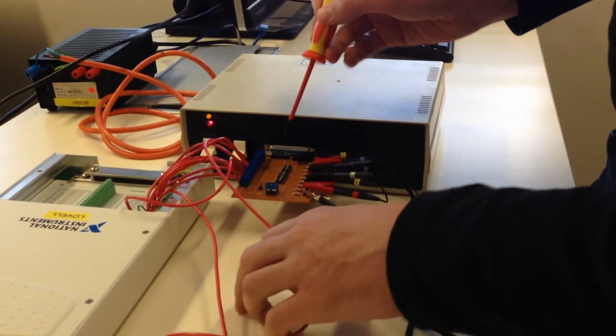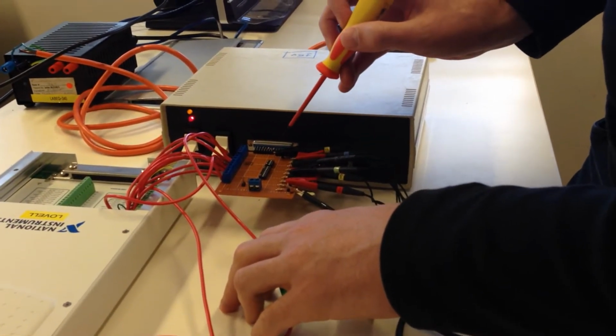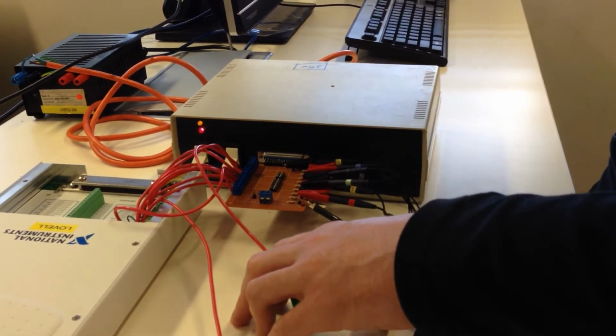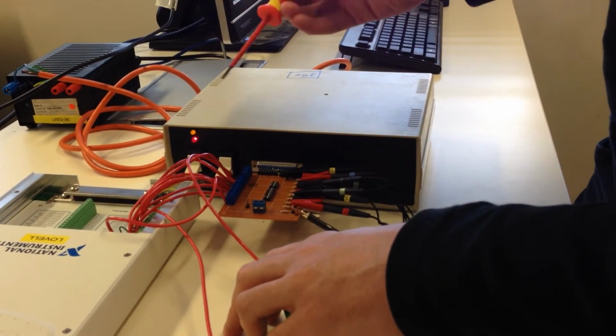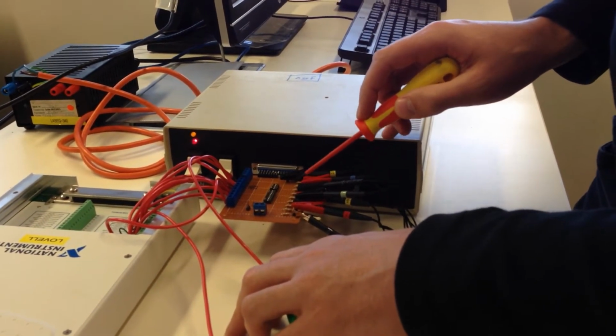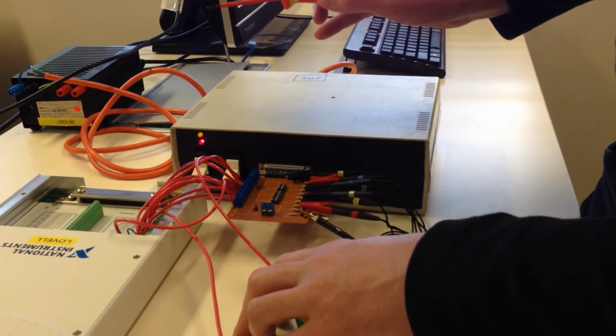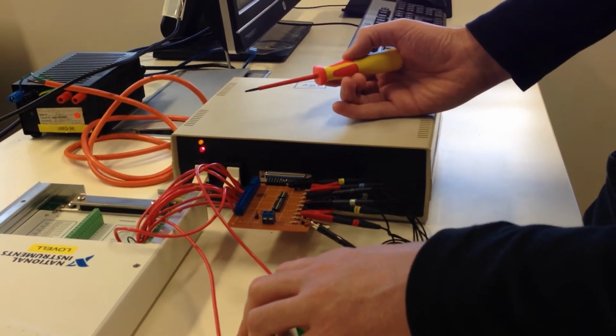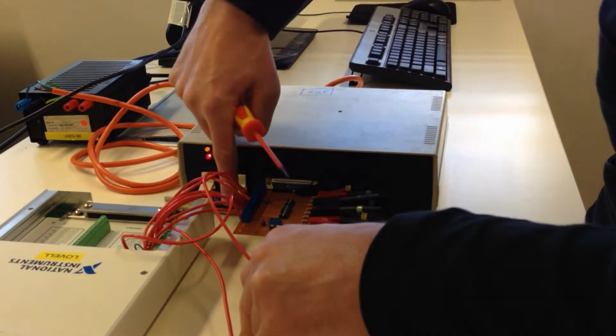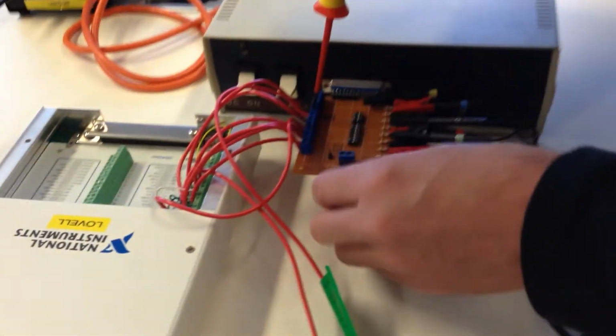Once you've done that first part, each of these resistors is 6.8 ohms, so if you measure the voltage, you know the resistance, you can figure out what the current is. You'll get a current value for every resistor, so you can average that across all of the 7 resistors in the middle. So when you finish that, switch off the current, get the demonstrator to come over ideally.